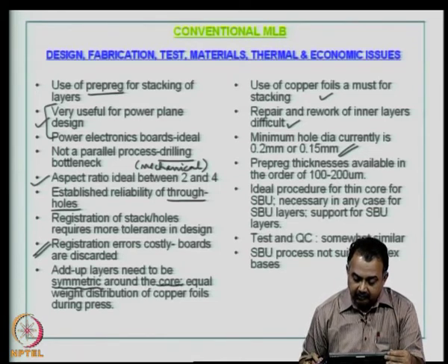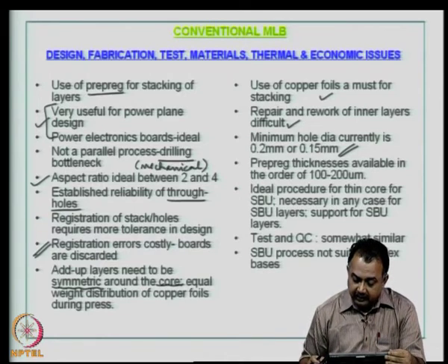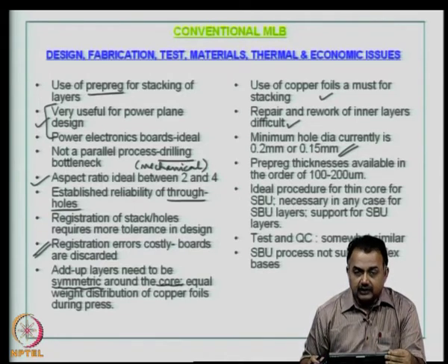Prepreg thicknesses are available in the order of 100 to 200 microns. So, you can vary the thicknesses in the build up according to your design. This is an ideal procedure for thin core for SBU.